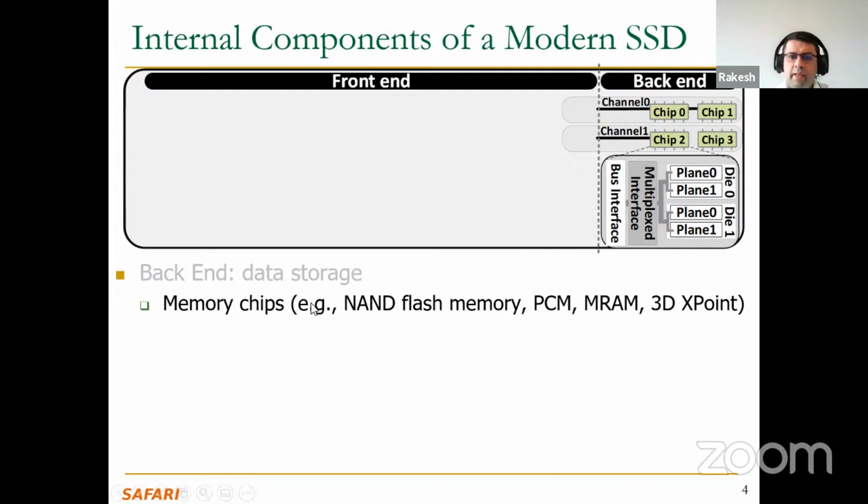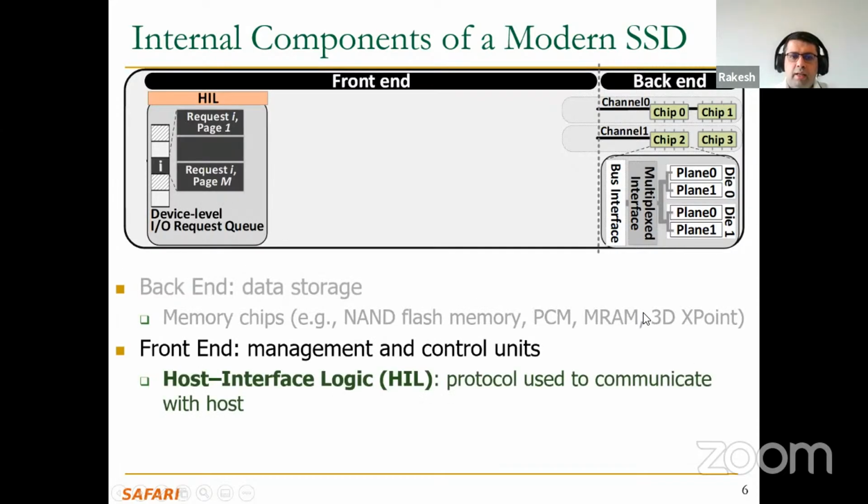Typically in storage we have NAND flash memory, but we can also have other technologies like PCM, MRAM, or 3D XPoint. Then we have the front end, which houses the management and control units. We have the host interface logic, which implements the protocol required to communicate with the host system to which the device is connected. It has a device-level IO request queue, to which all the requests come from the host.